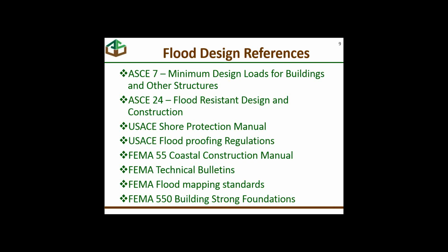It does not have load information in it, but it does have information in it related to issues important in design. So it does have sections on deep foundations and pile designs, talks a fair amount about scour and erosion and how those can be determined, etc. And talks about not only foundations, but lots of other issues related to flooding. The Corps of Engineers, which are the next two documents, have design manuals. The Shore Protection Manual is huge. It's on the internet. It's available for free, but there's a tremendous amount of information available there.